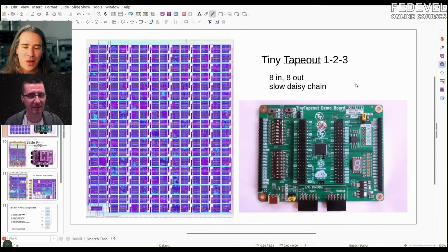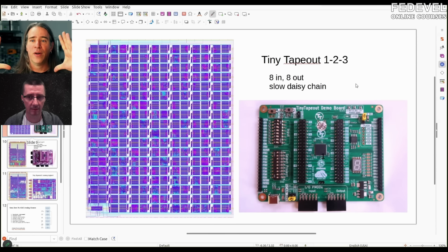Okay. So it was like a lottery. You could design things using these open tools, but were you going to get an actual chip? I don't know. So the question was, how do we get people to be able to do their chips easily? A multi-project wafer is a wafer in which you get a small bit and can get your own chips. So it's shared, so it's cheaper. But Tiny Tapeout split that up. This is one chip out of that multi-project wafer, and each of these little squares is a project. Someone did a different project. So Tiny Tapeout ended up working with eFabless to do this more regularly and more guaranteed. It's not a lottery. You got those tiles, they're yours.